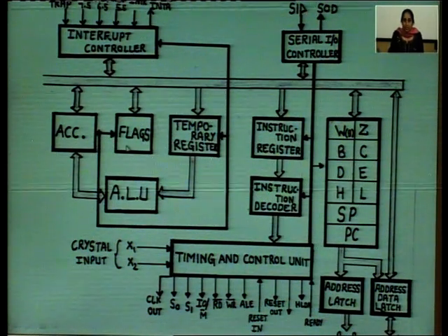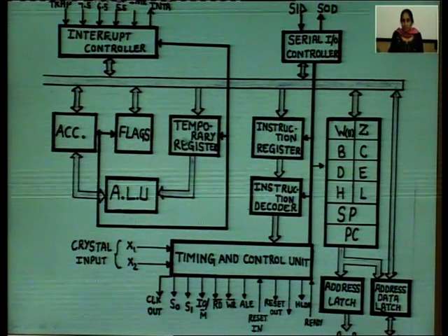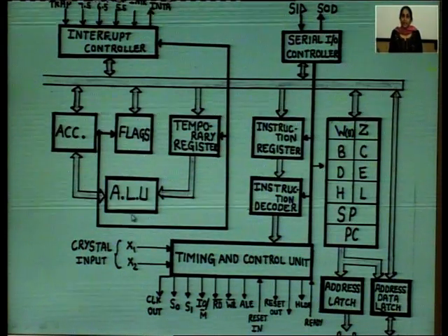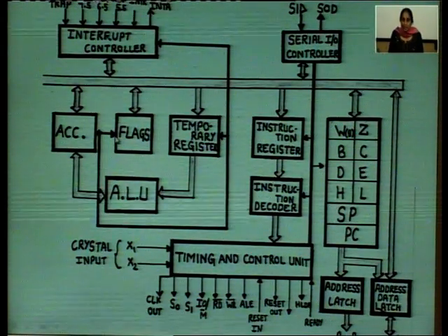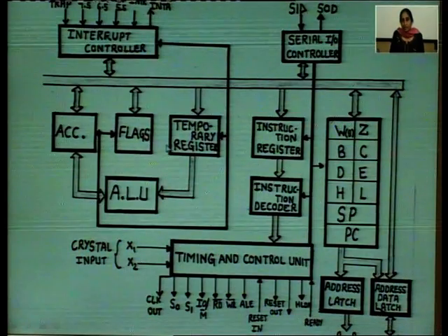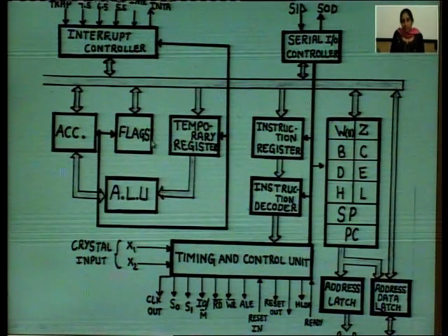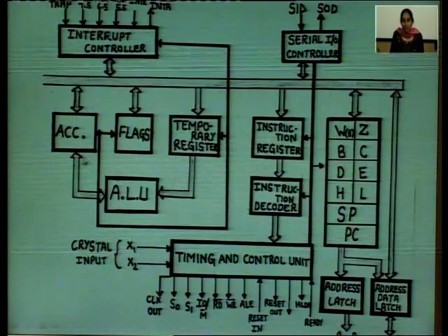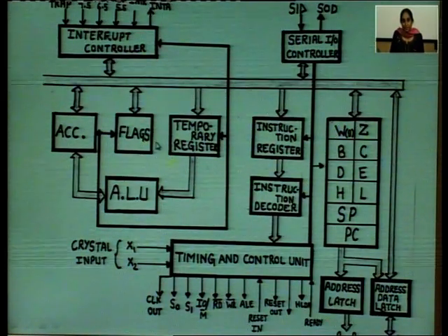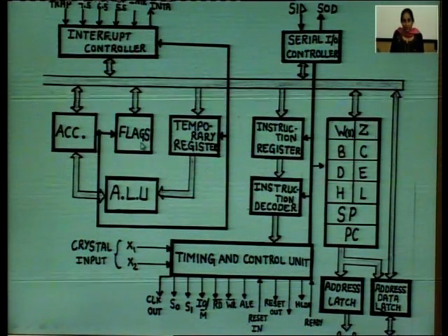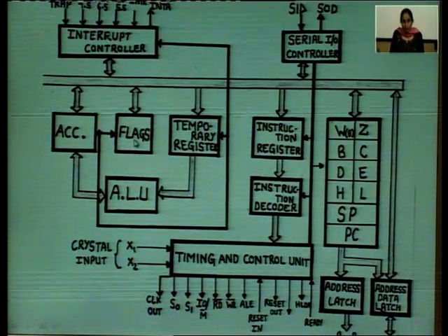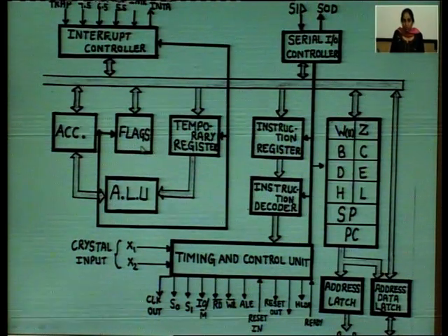According to the results of various operations performed by the arithmetic and logic unit, flags in this register are set or reset. In this register, 8 bits are there, but only 5 bits are used. Here we have 5 flags: sign flag, carry flag, auxiliary carry flag, zero flag.